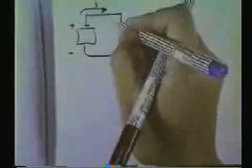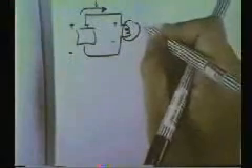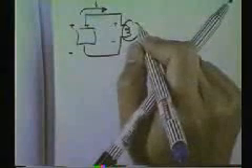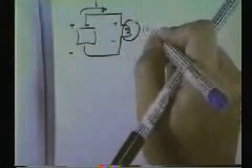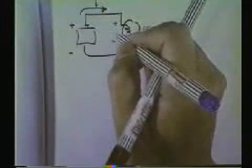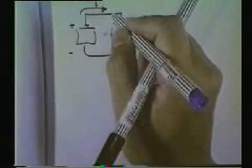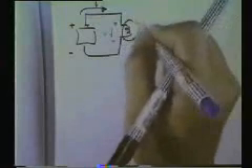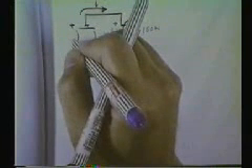It will be plus here, minus here, right? So this one absorbs the power. I said this one is 100 watt. In this case, the direction of V is this way, right? And V and I in the same direction generate the plus power.